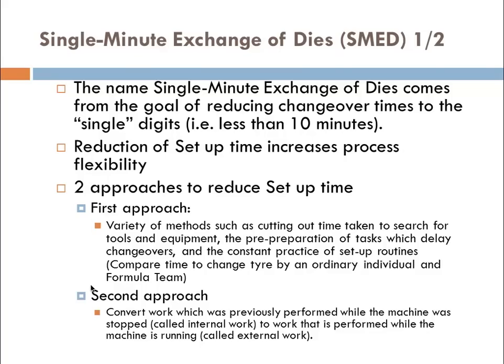The second and common approach to setup time reduction is to convert work which was previously performed while the machine was stopped to work that is performed while the machine is running. So the work which was previously performed while the machine was stopped is called internal work, and the work that is performed while the machine is running is called external work.